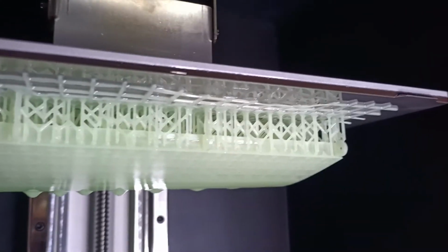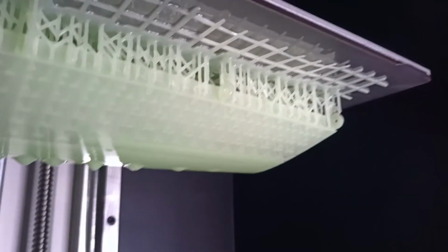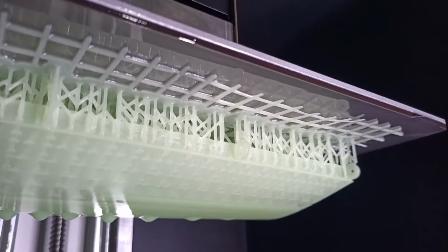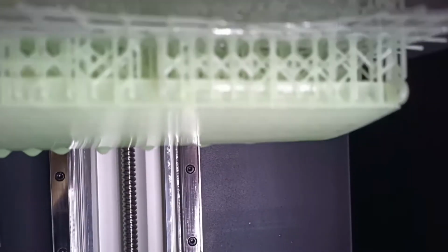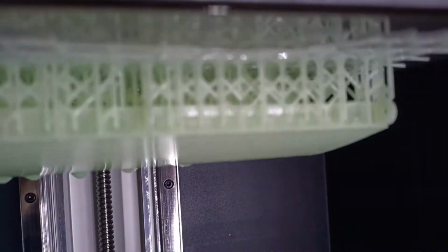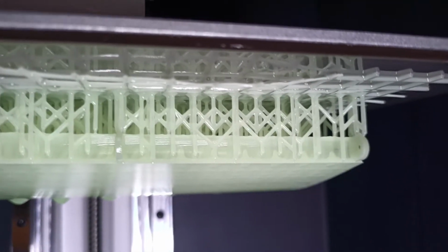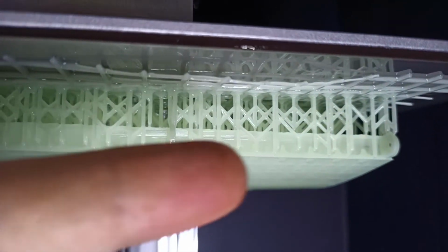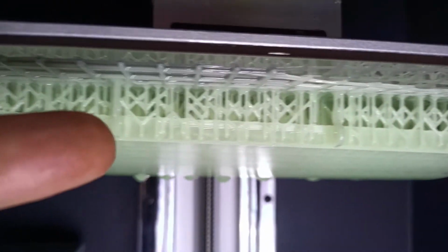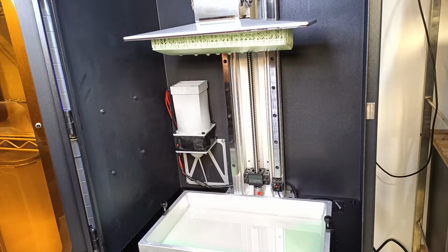So the issue that I've been having is with bed adhesion. So you see here where the raft is peeled away, but because I'm now using this grid raft, you can see that even though the raft has lifted off at the top here, the part itself is printed very nicely on that back edge, on the aileron hinge. So I'll show you now just how much of that resin is actually trapped in there.